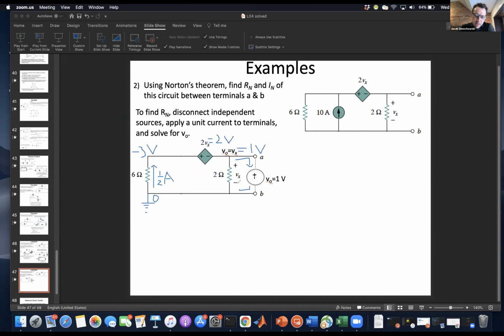And maybe that's why the test current was applied and not the test voltage, because in this picture, if you wanted to do a KCL equation at that point, it's not possible because we have no way, like this is sitting at 1 volt and this is sitting at 1 volt. And so there's no voltage difference here, but there's also no resistance. And so you have a 0 divided by 0, right?